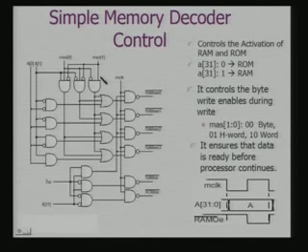That is depending on the size of the transaction, and depending on this address, one or more of these RAM write enable signals will be activated. And this is a way by which your size information has to be made use of, because you need to know for a bus transaction what is the size of the data transfer that is taking place.